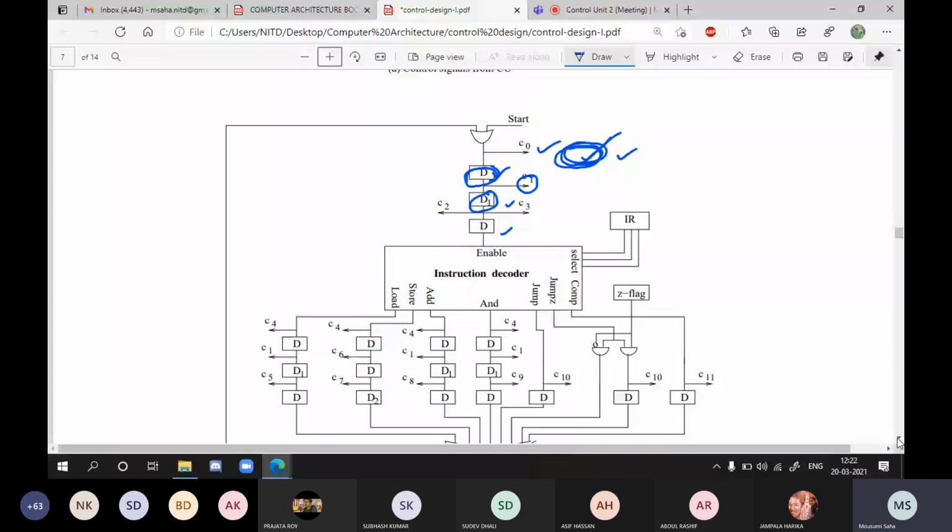So these two are the internal components of your microprocessor. You know that the memory access time, that means memory read and write operation, will take more time than this type of operation. So obviously D1 is more than D. This D1 involves the memory read operation. Whenever the processor does a read or write operation for memory or some other input output device, it takes much more time than the internal operation of the processor. So for that reason, here we can consider another delay, that is D1.